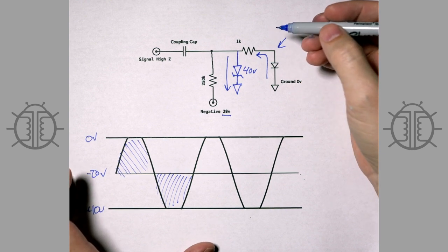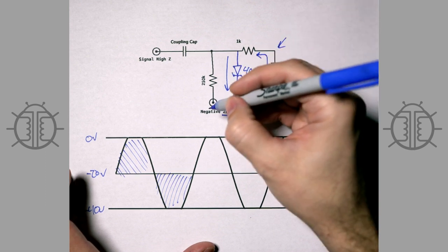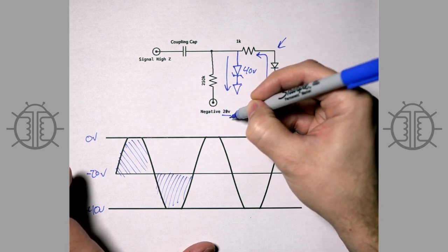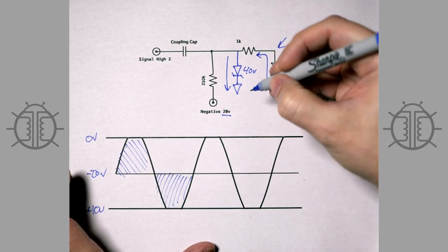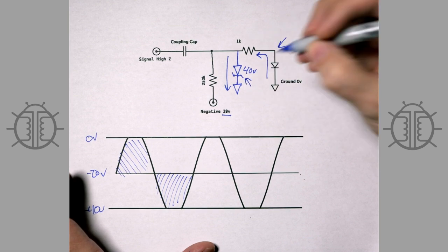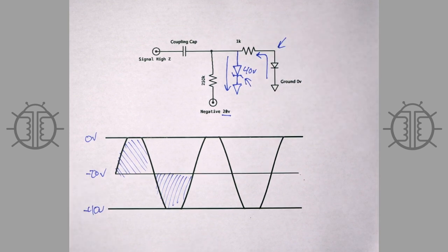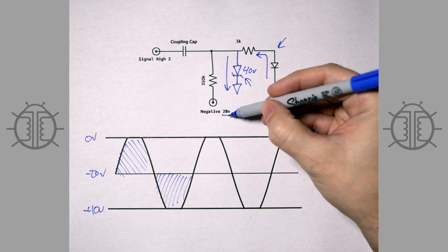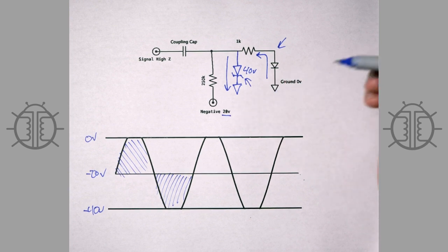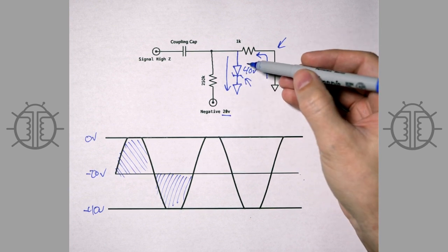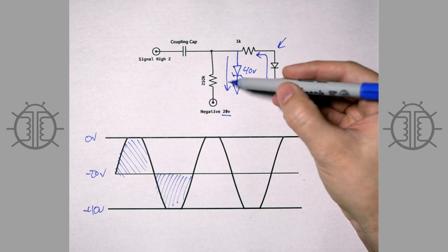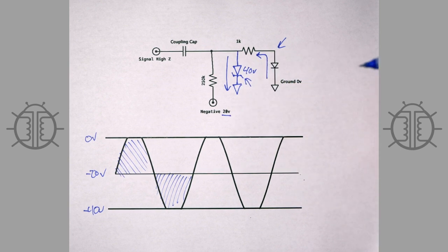I've tested this on the breadboard and it works fantastically, except for, you're probably seeing the problem. The major problem is that if you want a different negative bias, you have to change the value of the Zener, which is not practical, because obviously as tubes age, different tubes need different negative bias. As tubes age, they require less negative bias for the same current.